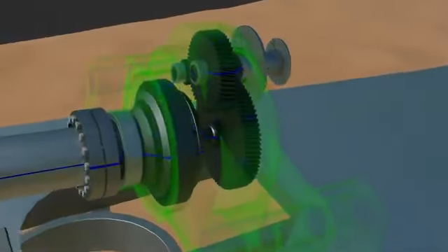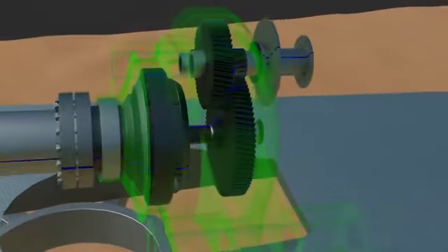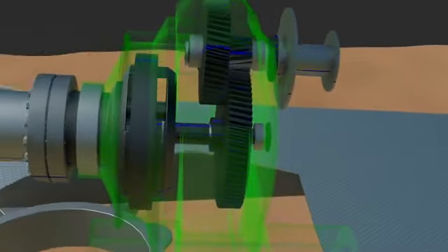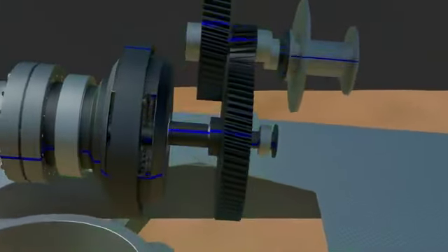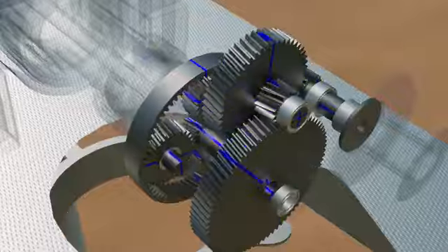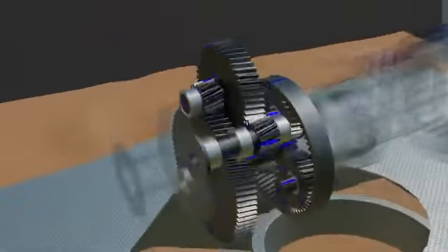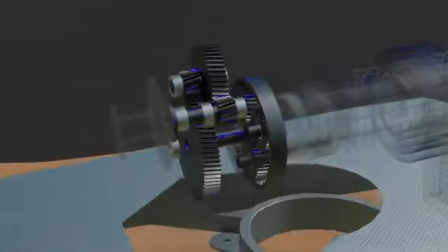In this model, a three-stage gearbox is employed, featuring one planetary stage and two parallel-axis helical gear stages. A planetary gear system is preferred for the high-torque input stage because the load is distributed among multiple planet gears, typically 3. In this model, the planetary stage has a gear ratio of 6, and the parallel helical stages have ratios of 5 and 3.3. Overall, the gearbox increases speed by approximately 100 times relative to the input speed.